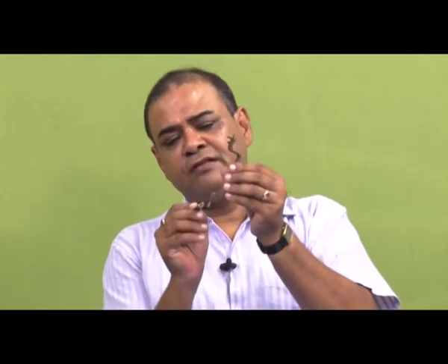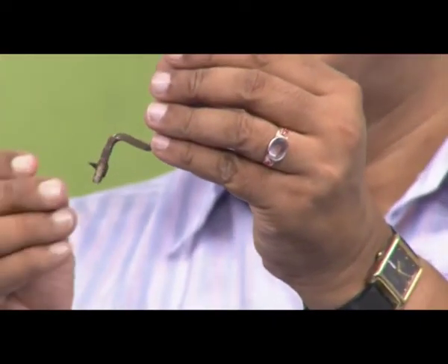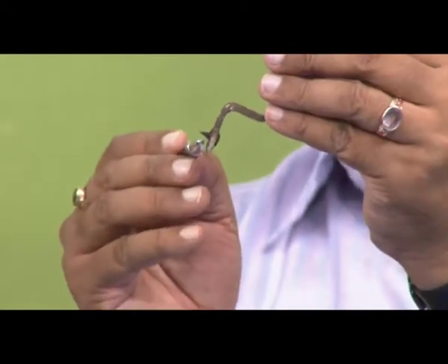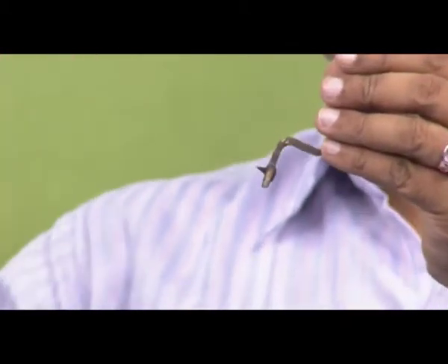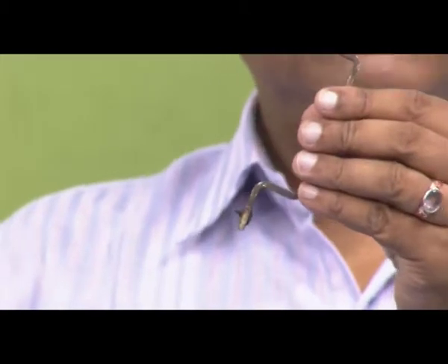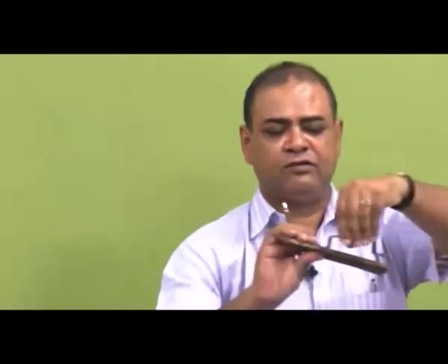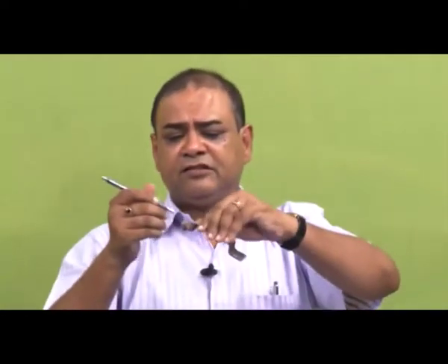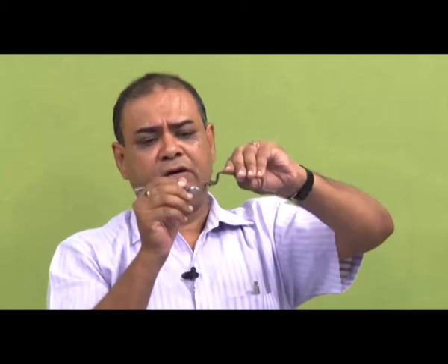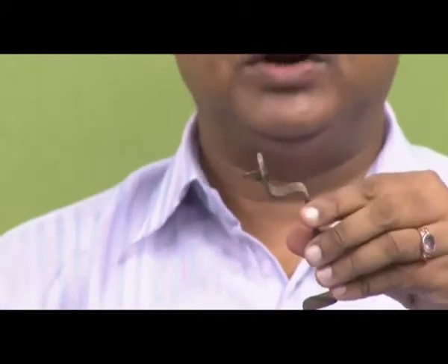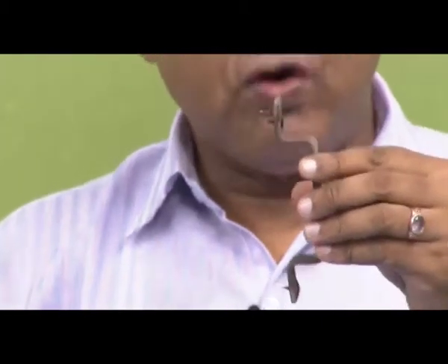And if you see this one, some part has vanished because the corrosion was so severe, it got lost into the atmosphere, while some remained in that particular wooden part, because it was fixed like this on a wood. Now, why is there a little bit of corrosion on top, but the part which has entered into the wood has a lot of corrosion? This can also be explained by using this concentration cell.